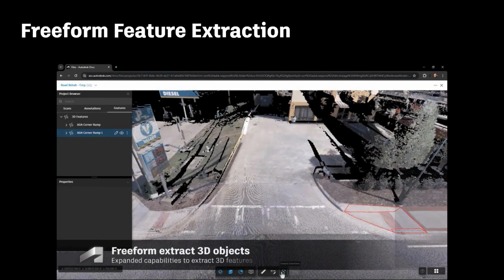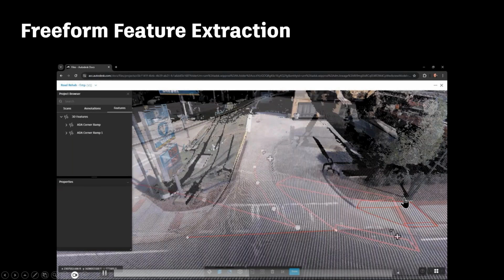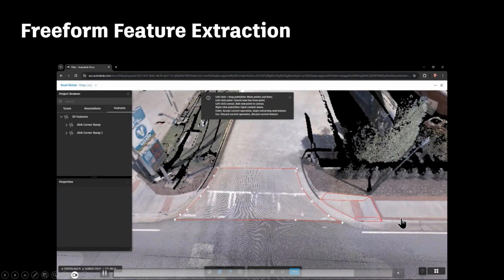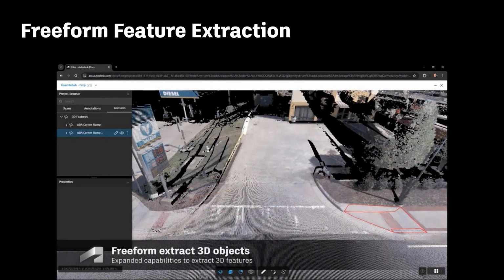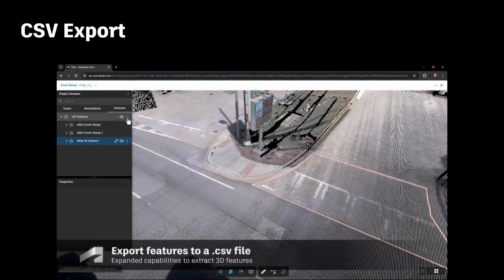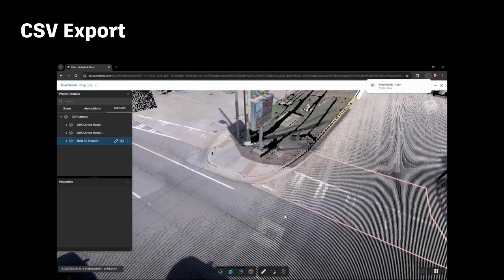So we've got a little bit of sidewalk, ADA ramp over here where there's our little detection strip, but then also grabbing part of that intersection as well. So giving you the different options depending on what you want to capture, how you want to capture it. And this is just showing that CSV export, and it's going to come across as your northing, easting, elevation, point number, description, the familiar format that we're used to seeing inside of Civil 3D.